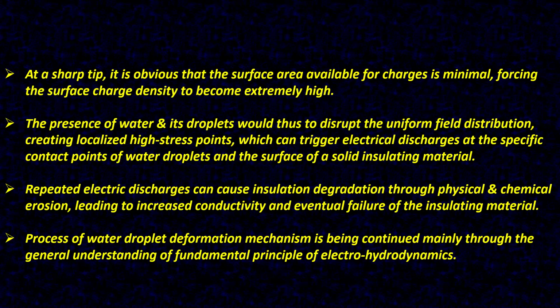The presence of water and its droplets would thus disrupt the uniform field distribution, creating localized high stress points which can trigger electrical discharges at the specific contact points of water droplets and the surface of a solid insulating material. Repeated electric discharges can cause insulation degradation through physical and chemical erosion, leading to increased conductivity and eventual failure of the insulating material.